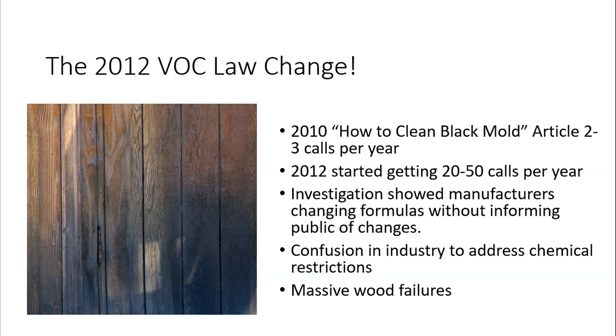And what we found out was that manufacturers, when the law changed in 2012, the EPA did not pass a national law. They passed a law that says the states have the right to say. So each state adopted the VOC law at a different level. Some of them said 550 was allowable. 550 is a good oil-based penetrating stain. Now, some of the states like California are saying it can't be more than 250. Some of them are saying 3. Some of them are saying 150. I think California's at 150.